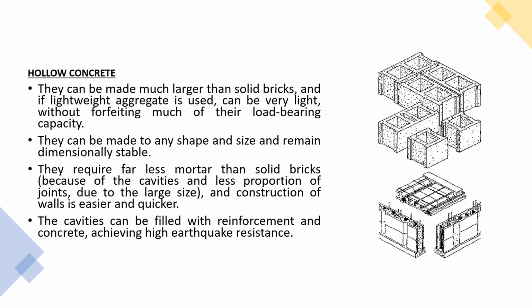They require far less mortar than solid brick because of the cavities and fewer joints due to large size, and construction of the wall is easier and quicker. The cavities can be filled with reinforcement and concrete, achieving high earthquake resistance.